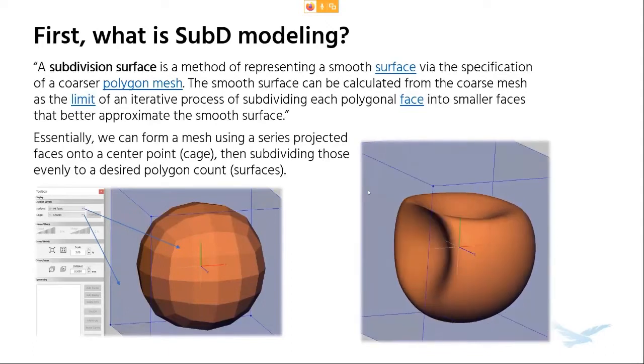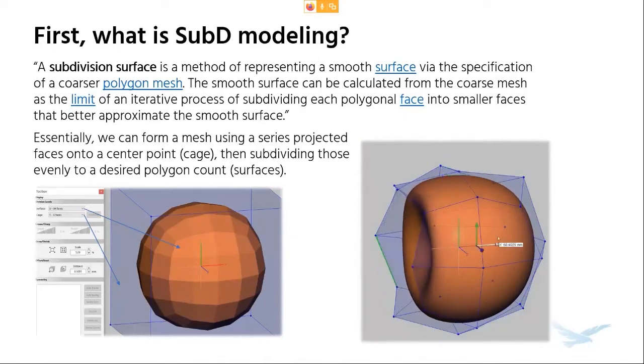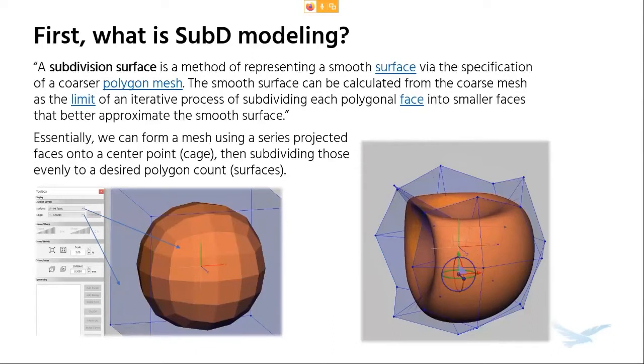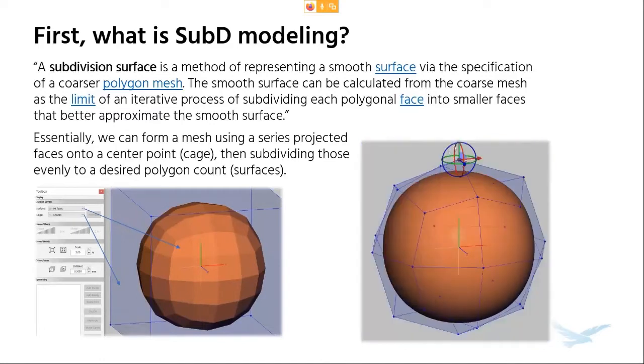Whereas in freeform, I'm able to just change the cage size, maybe make it a little bit coarser, move it around for big movements, change the density of the surfaces if I need, to really create these freeform shapes. And this really plays a role in spoiler design, and why we were inspired to make a spoiler is because traditional spoilers, from what we've seen on the market, are made just like I mentioned, with splines and tangential points and extrusions, whereas now we were able to essentially hand carve a spoiler to fit this car.